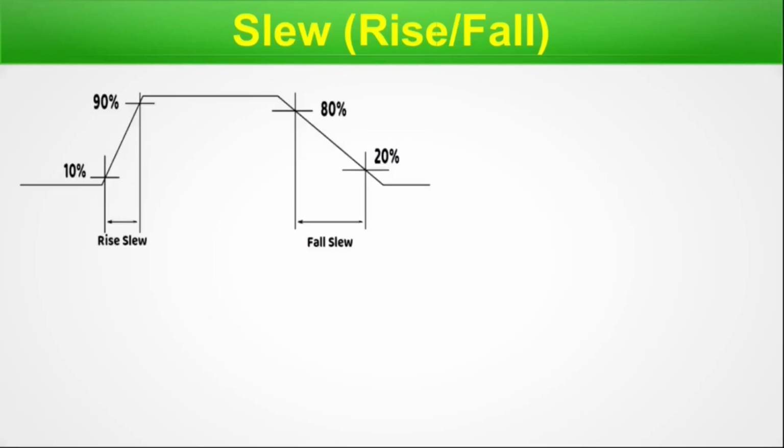So let's move on. Slew, rise and fall. In this particular slide, we will discuss the most important element in STA, that is slew. We will take the help of an infographic to understand it properly. So here, this is our graphic. Now let me bring my mouse pointer. So here you can see the waveform is rising. Here it is flat, and then it is again decreasing. I have intentionally kept the two inclinations different, just to show you that in real life they may be different. And I have also exemplified different kinds of thresholds, right?